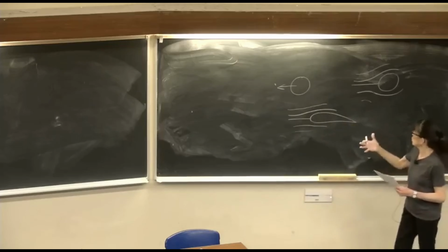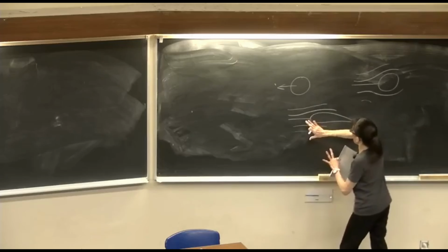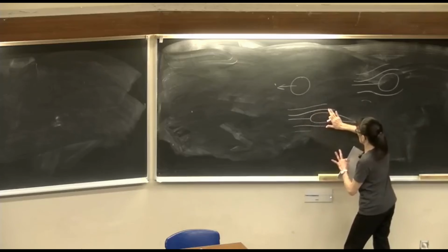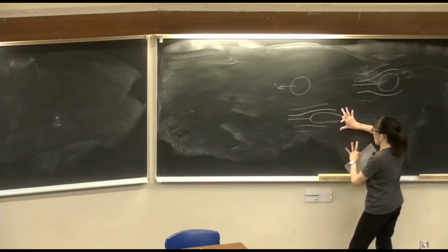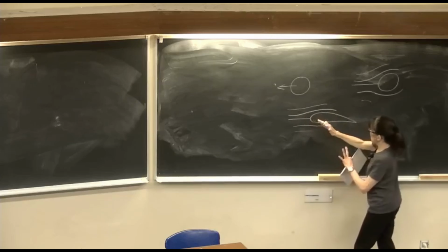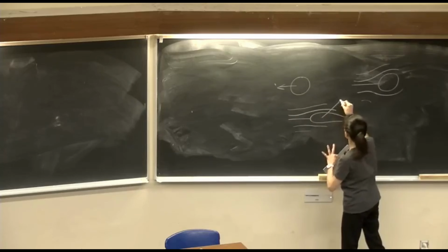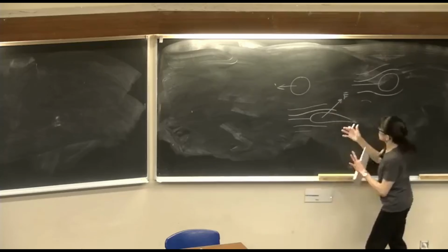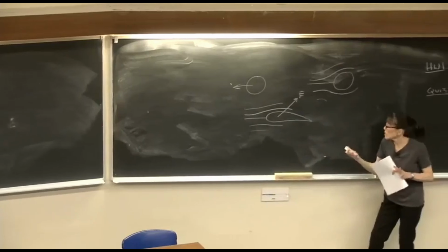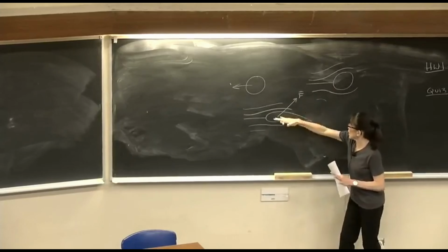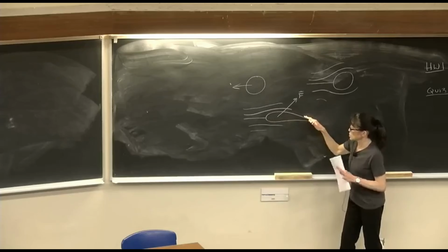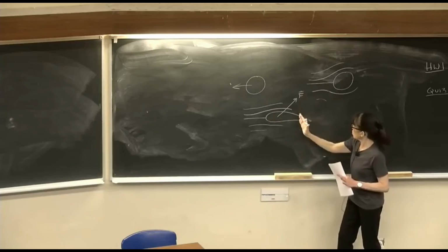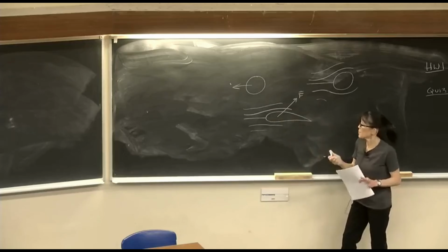But in any case, the point I want to make is that based on relative motion and the behavior of the flow, there will be a net resultant force on the object. And as I mentioned, that may be the objective of the analysis. We could break it down and have the component in the direction of the flow, which would be the drag force, and then the component perpendicular, the lift force, etc.